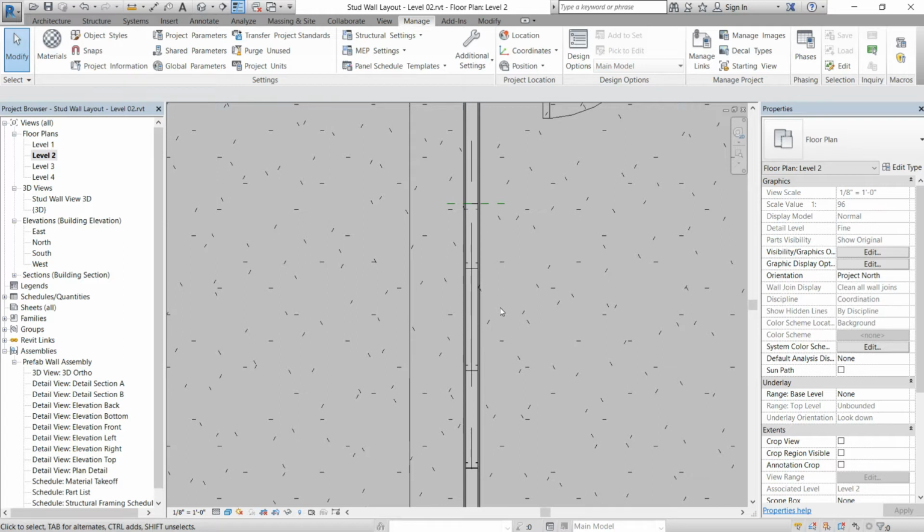We're going to create almost like a surface, I guess, something for plywoods, and when we create the surface, we're going to have it calculate the area, so that way when you generate it, it will actually tell you. So if you had to cut the plywood in half, it'll tell you the amount of area and the dimensions of it that you'll actually need. So you'll need like, let's say, a 2 foot by 4 foot piece of plywood. It'll call that out for you, and then you can give those also mark numbers, and schedule everything through your material list down here, your material takeoff.